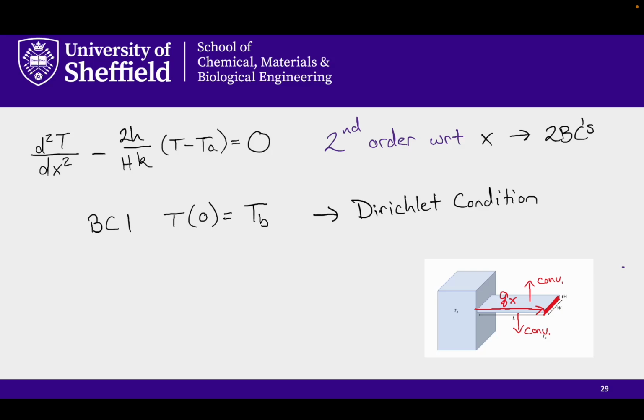but it's going to be so much less heat transfer than all the other heat transfer in the x direction, because conduction is really, really fast. It transfers a lot of heat, and convection from that little tiny surface area is going to be very small. So we make an approximation and we say that the flux at the very tip of the fin is basically 0.